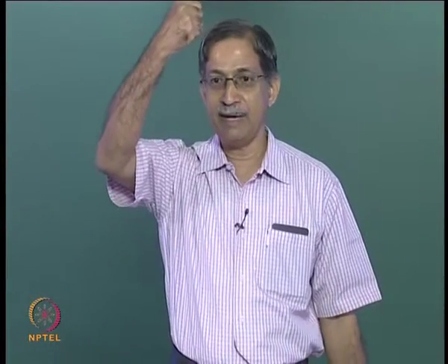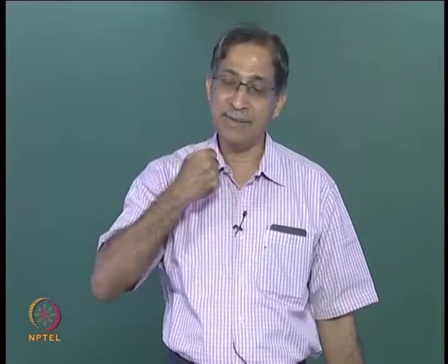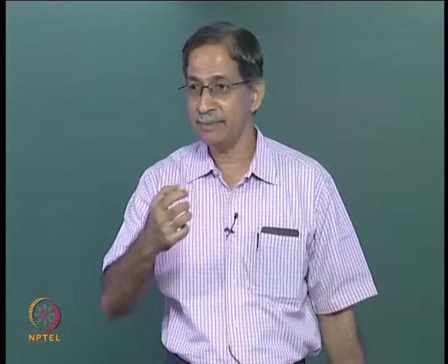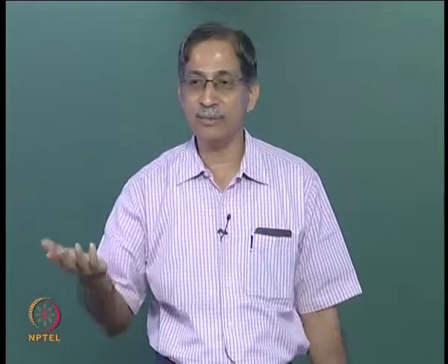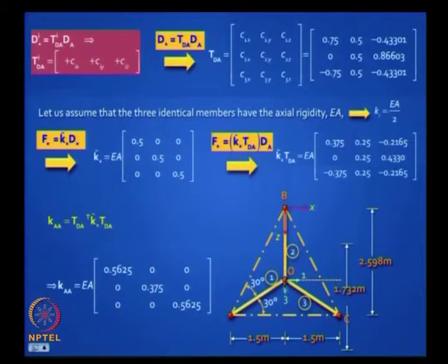When I pull something up, will it have any displacement in the horizontal plane? No. So it makes sense. So you have proved intuitively that K12 and K32 will be 0. So that proves something. Okay, now you apply a force F D3 equal to 1, put a displacement D, you pull it, okay. Do you think vertically there will be any movement?